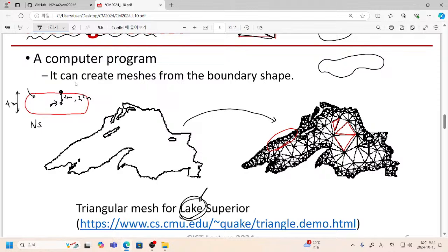So can you say that 2 nanometers is far away from the interface and we don't have to care about it? No. Since we have seen so many scaled structures, at least the channel region should be discretized quite reasonably. Otherwise, you will have quite poor results for your discretized solution.